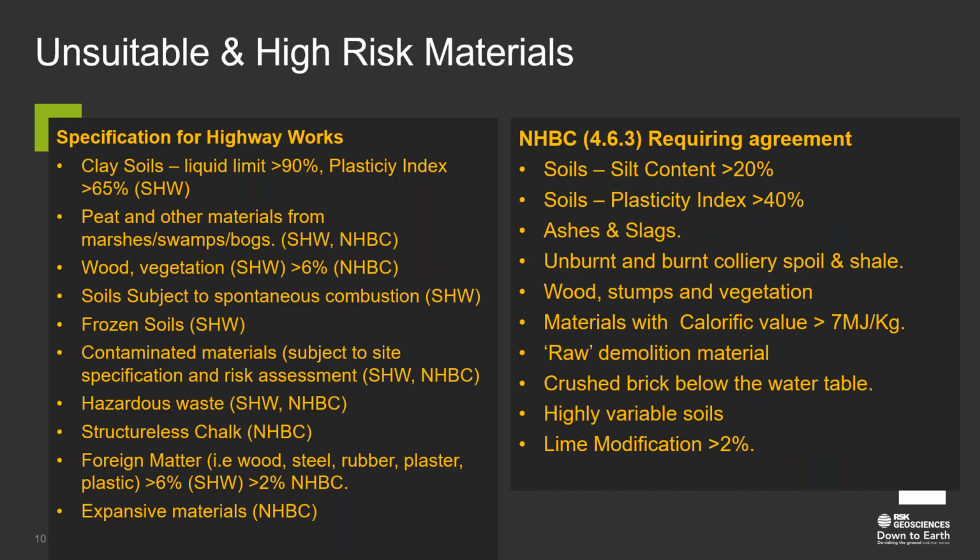So once we've done this, we first of all need to decide, can we use the material at all? Is it an unsuitable material? Is it basically a high risk material where we might need to do more work? And you can see here quite a large list of unsuitable material taken from both the Specification for Highway Works and the latest NHBC guidance.